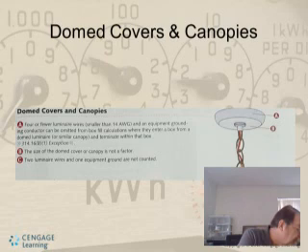If there are 4 or fewer luminaire wires smaller than 14 gauge, and the equipment grounding conductor, they can be omitted from the box fill calculations where they enter the box from a dome luminaire or canopy. The size of the dome cover or canopy is not a factor, and 2 luminaire wires and 1 equipment ground are not counted. Essentially it's saying you don't have to worry about it. Just put a standard box up there and mount it properly, and you'll be okay, as long as you don't have a lot of conductors going through.